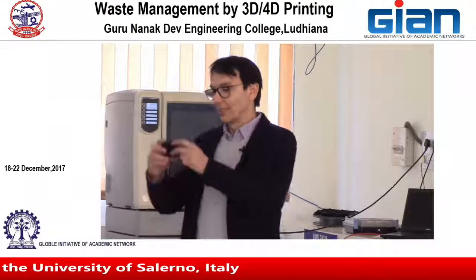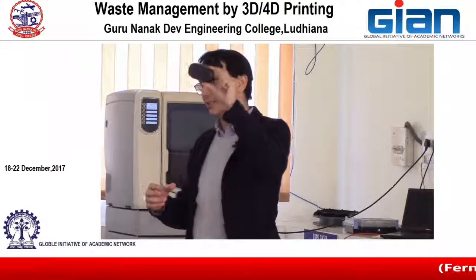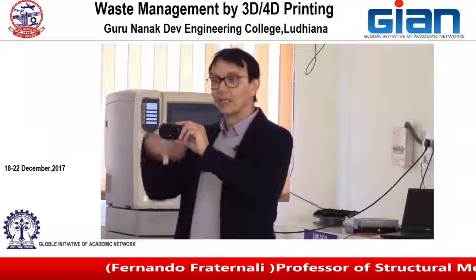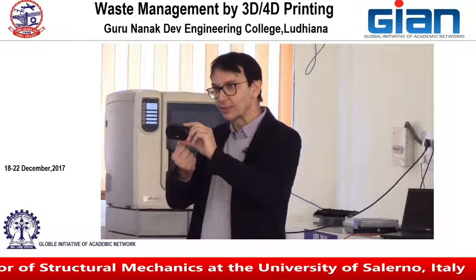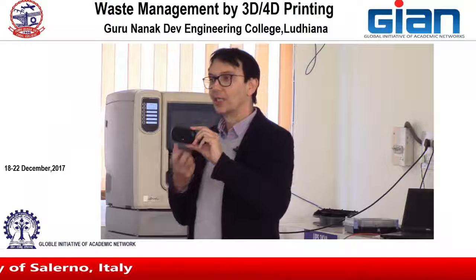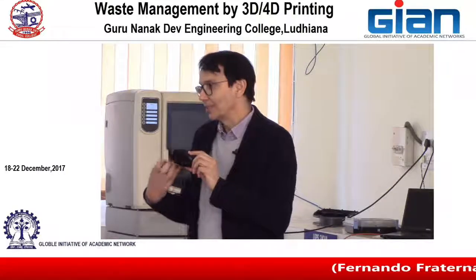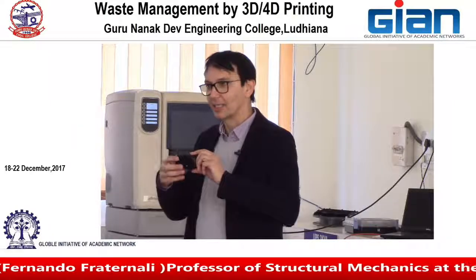Assume this body has a given initial energy. Then we ideally open a crack, we spend some energy to open the crack, and we gain some energy due to the reduction of the stiffness of the body, because the body becomes more compliant, so we gain some elastic energy.